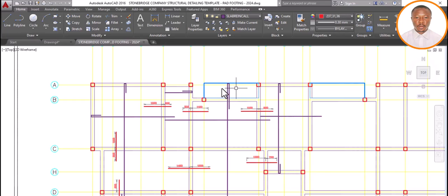There's a principle that says that the length of your cantilever is multiplied by 1.5. And whatever the result is, that's what is going to enter into your slab in order to be able to withstand the force outside here. For example, if from this point to this place is 1.5, and you also put 1.5, the force here can cut off the reinforcement, or cause a shear here. And that is why that principle needs to be applied here.